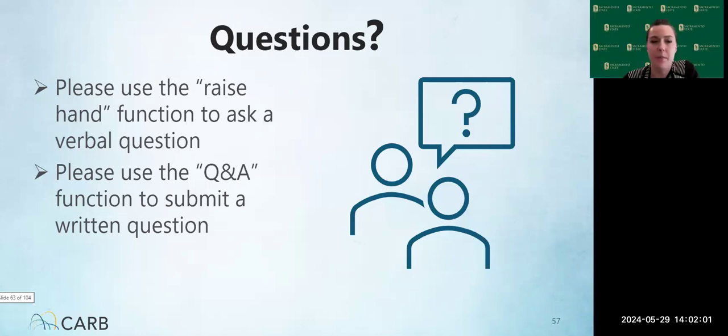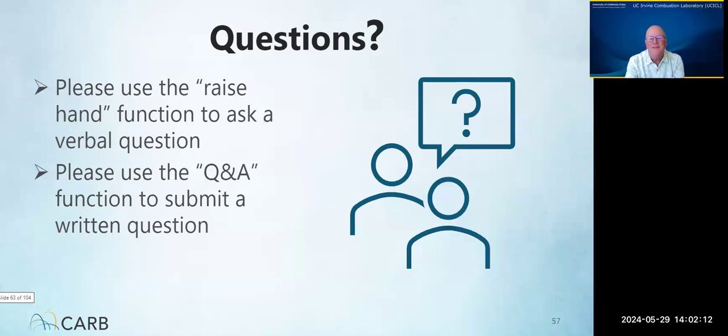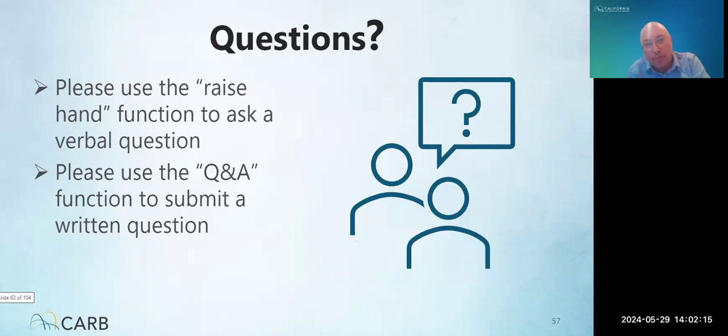We have a question from Paul Rangel. Is there a CARB-approved list of DPFs for CHC applications? Andrew? Yeah, sure. So CARB doesn't approve DPFs. CARB would verify the performance of the DPFs. And there is a CARB verification regulation. There's a verification program and a team at CARB. It's the freight approval section that is implementing that program, and they do have a public-facing website with a list of verified devices that are in other sectors such as stationary or on-road.